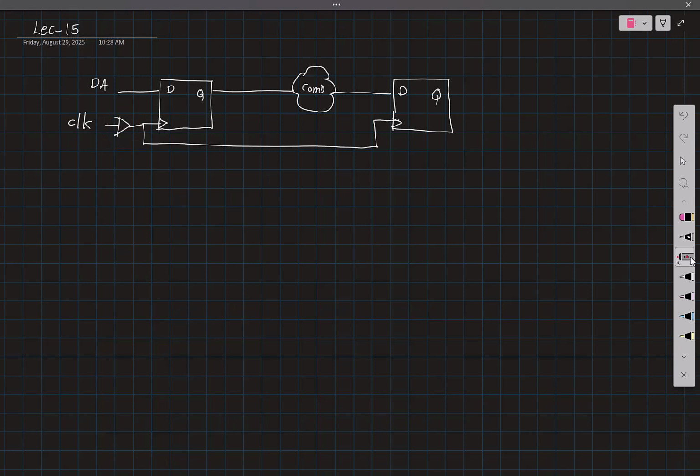In this particular question, anytime you see a timing analysis question, you have to identify the path in which you are doing the analysis. So you have to identify the launch flop and the capture flop, right? Or something that is being launched and something that is being captured. And the setup and the hold constraints are now associated with the capture flop. You are checking if the data is getting captured correctly.